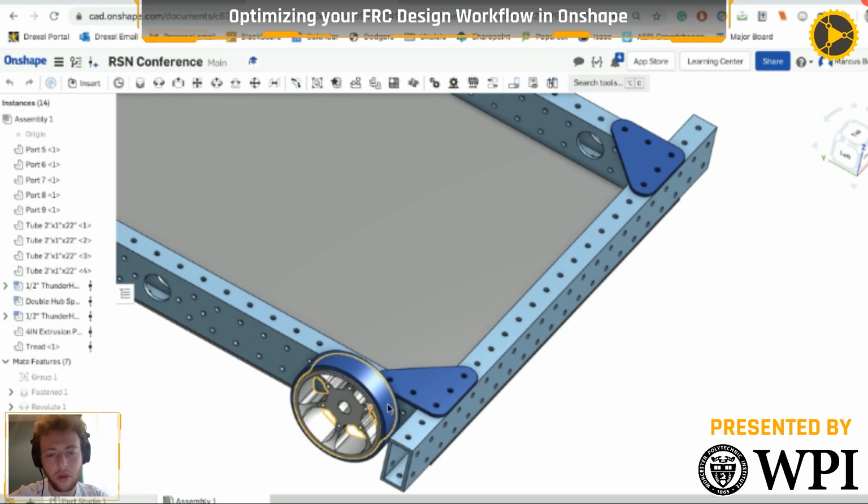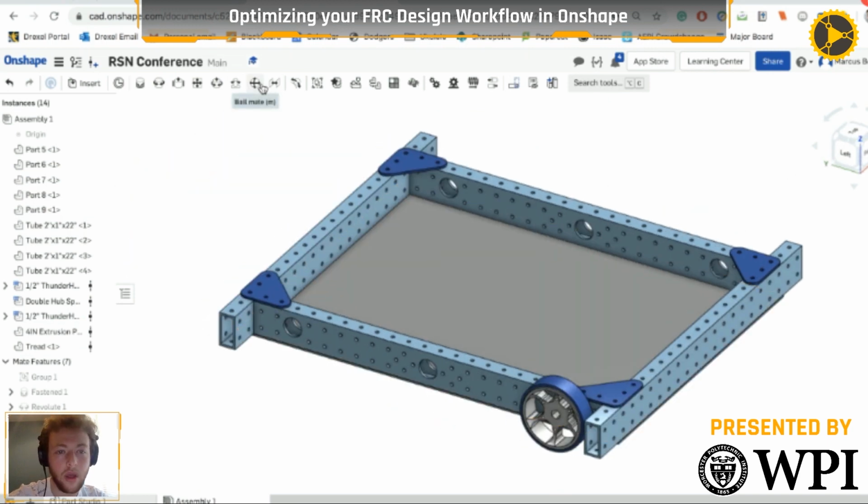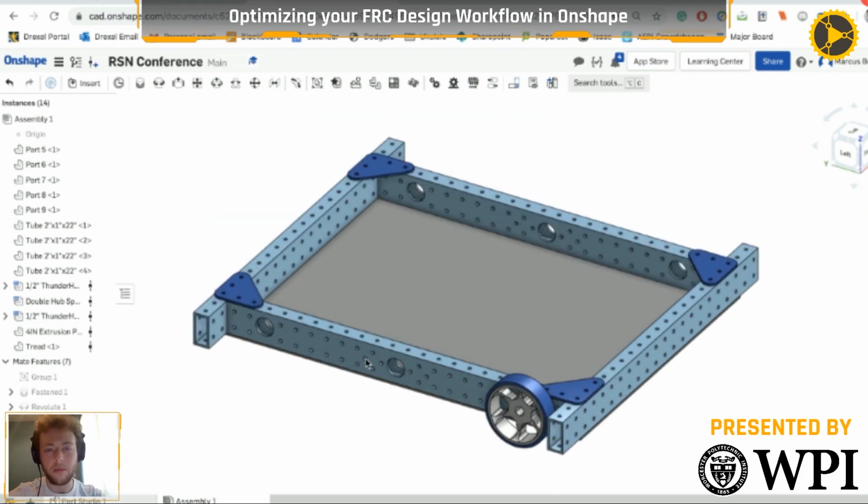So I can then create those. The workflow is a little different from SolidWorks or other platforms, but it makes life a lot easier. I'm going to use what Onshape calls the replicate tool to accomplish the rest of the stuff. It's going to be a little wonky because I have to delete a bearing, but it makes for some really awesome and easy additions to everything.